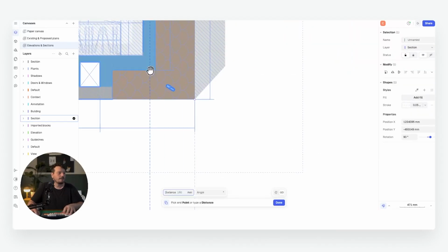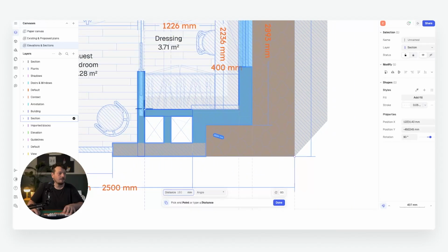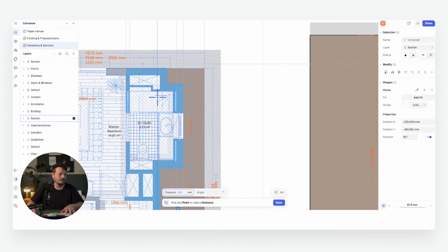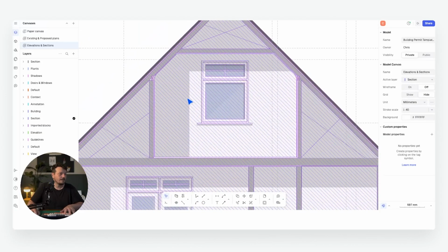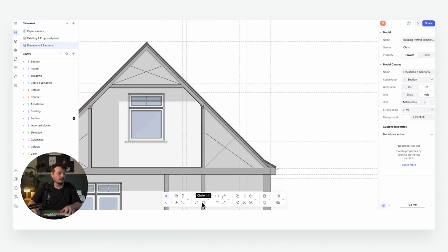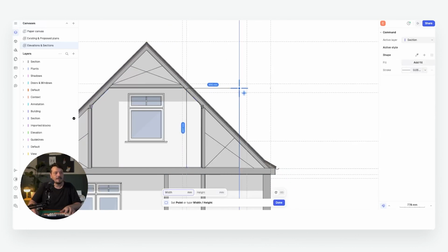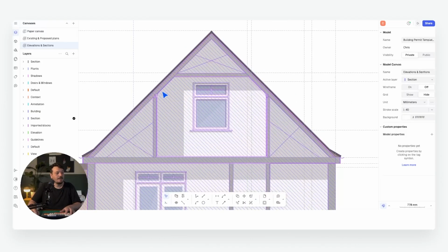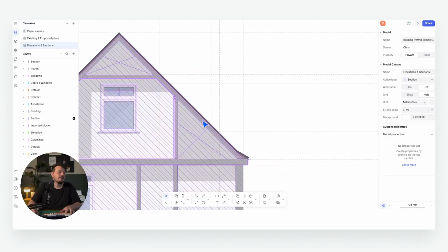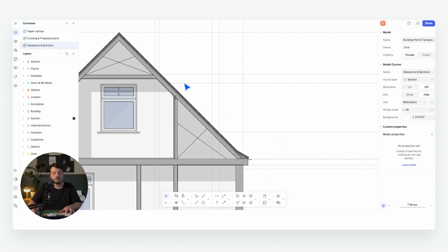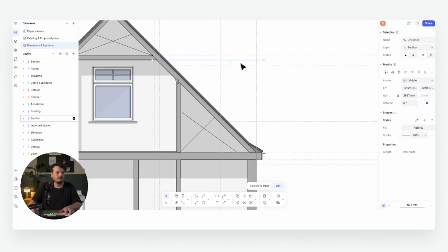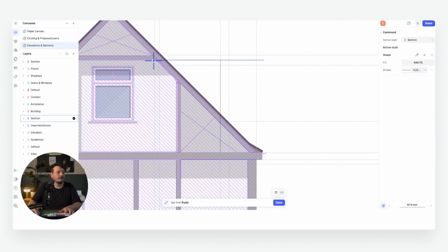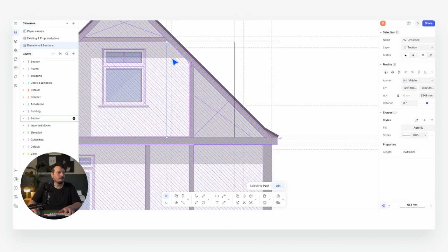So let's just go over to the floor plan. We're just going to set up those guidelines of that main volume of space that we're creating. And we can see it in here. So in essence, I'm going to be creating a new volume in this zone. I'm going to be pushing this vertical wall back down to here. The bed head can sit nicely in that recess, and I'm creating a full height space for the dormer. So you can see here, we'd continue that ceiling level in there. We've got our edge of our dormer here, and then we've got this new internal wall in here.